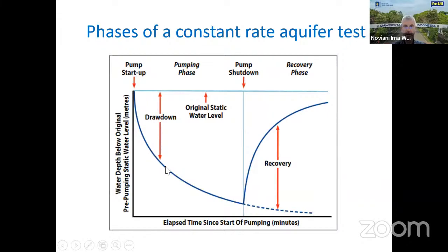The longer I pump, the more drawdown I get, okay? So remember, this is the original water level. This is what happens over time, okay? So the drawdown continues, go down. All right, so at this point, I decide the test is over.